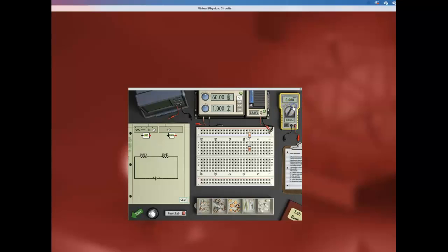Then I'm gonna look at this here. Oh no, this is the one. I can see amperes DC. Yeah, that's correct. And you will measure the current between the positive terminal of the power supply and R1. Then I will say this is going to be my positive. It should be here. And this is how I'm going to measure the current in series.